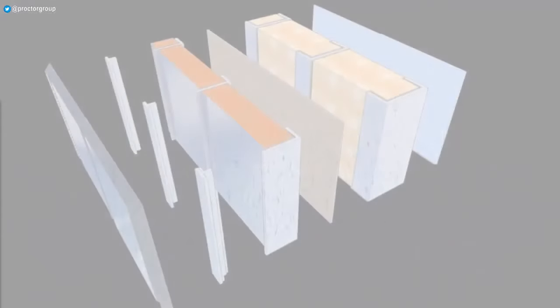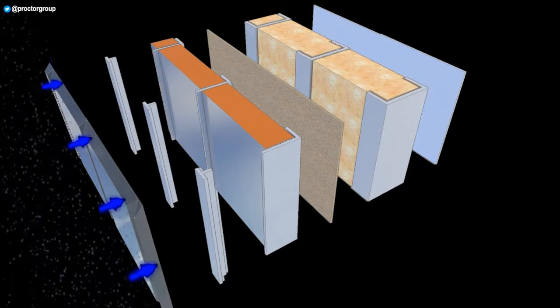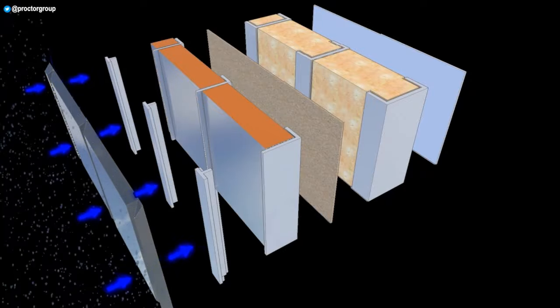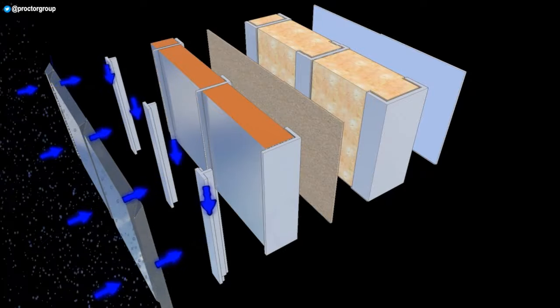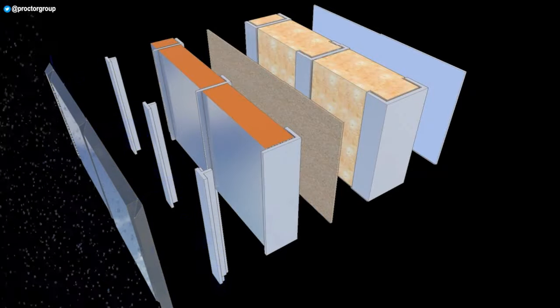There are a number of potential moisture sources affecting all building envelopes, the most obvious being the external environment, weather and rain. Most rain screen systems commonly used in high-rise residential and commercial construction are not designed to provide a complete barrier to water ingress. Therefore, the cavity behind should be provided with the provision for drainage to the outside, and care should be taken at design stage so that water may not track into the inner layers.